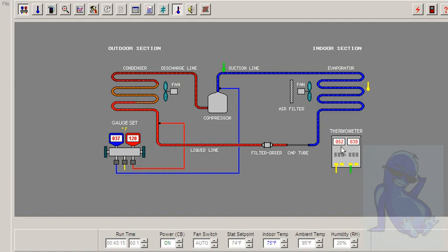Our supply temperature has actually dropped lower, so now our delta T is greater. And what happened to our superheat? Our superheat is now 39 degrees on the suction line and only 37 degrees in the evaporator, so our superheat is only 2 degrees. So when we drop humidity, we drop superheat. Good to know.